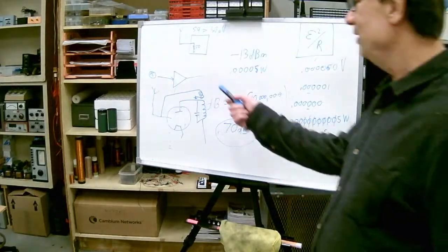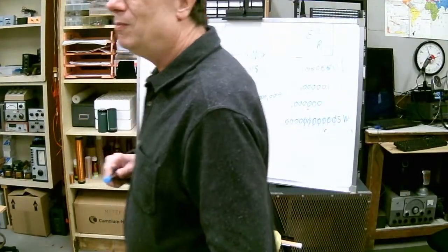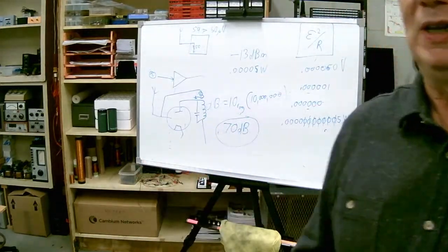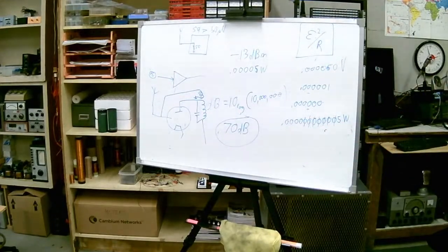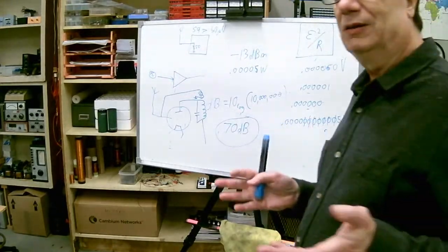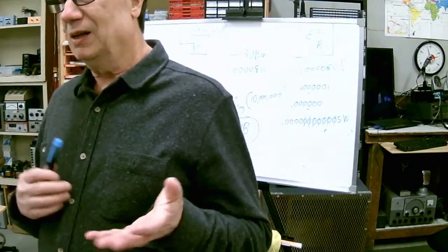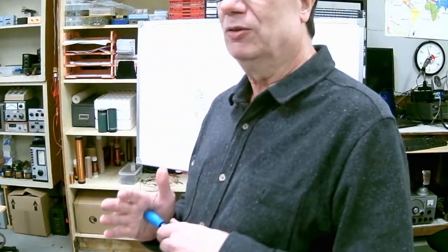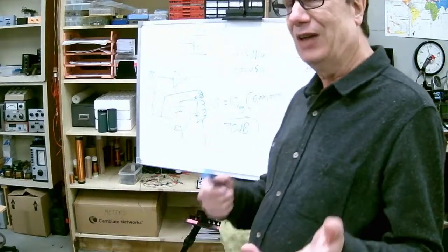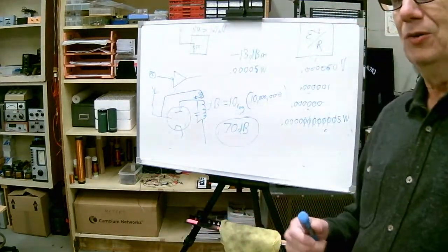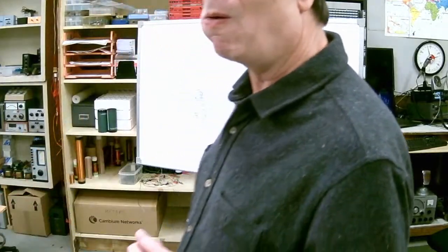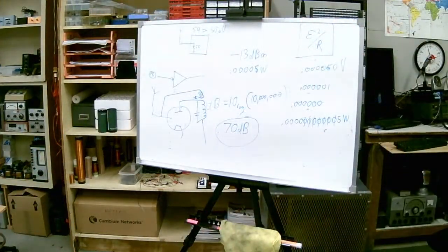So all your gain is right up at the front stage. Now, as receivers became more and more sophisticated, we moved the gain further and further downstream. So your state-of-the-art receivers, including cell phones, now are pretty much what we call direct conversion, where most of the gain is after detection. Gain, meaning amplification, most of that is done after the detection.